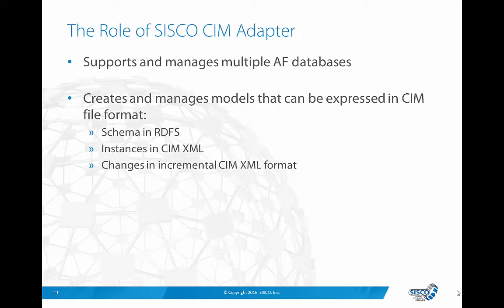The role of the SISCO CIM adapter is to support and manage multiple AF databases. It creates the element templates and other library information through a standard file format called RDFS. It creates instances, AF elements, through importing CIMXML.